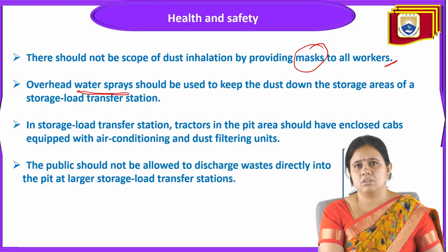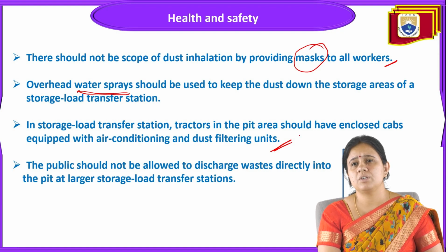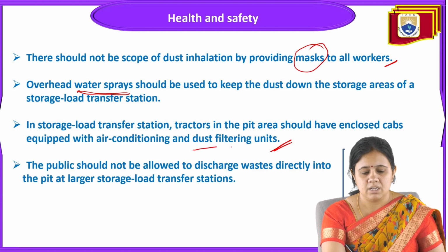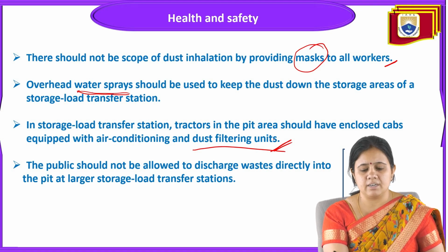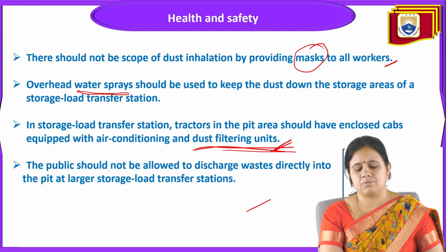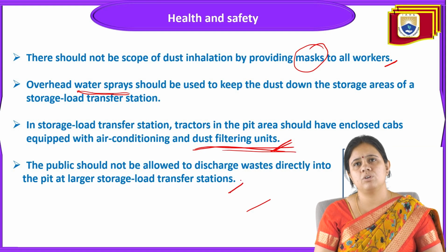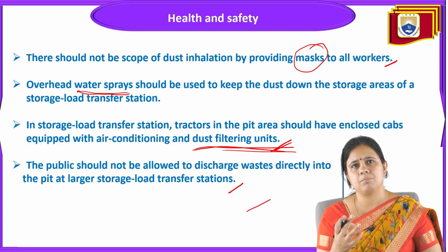In a storage load transfer station, tractors in the pit area should have an enclosed cab equipped with air conditioning and a dust filtering unit. Next, the public should not be allowed to discharge waste directly into the pit at a large storage load transfer station. So these four are the important points related to the health and safety point of view.